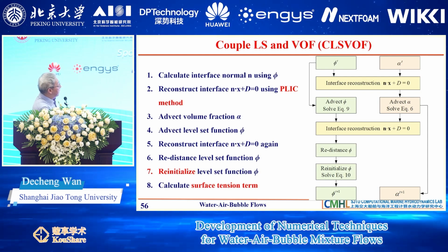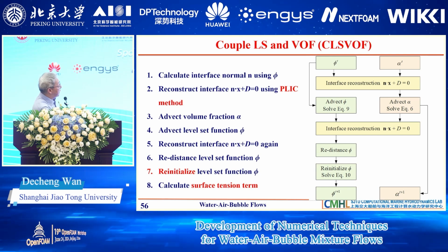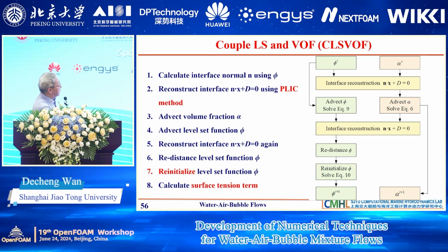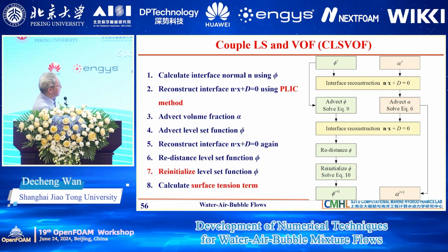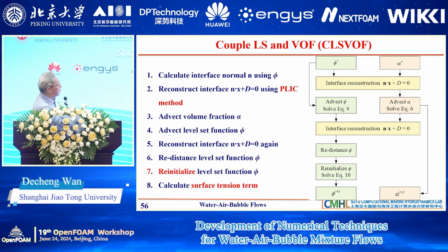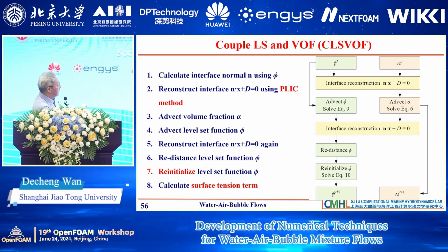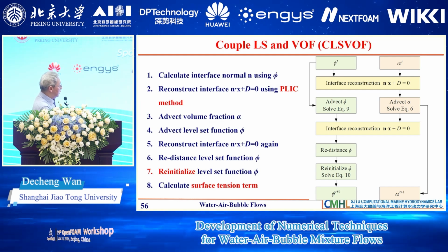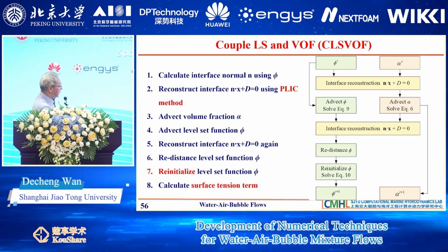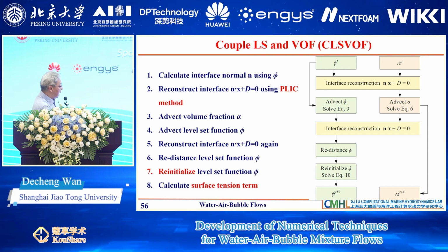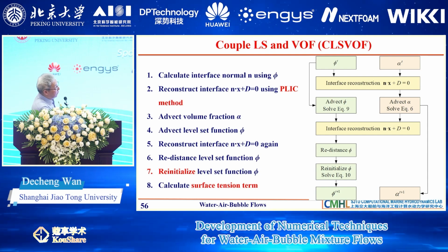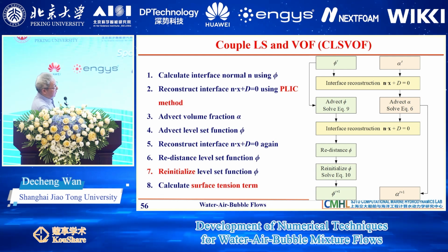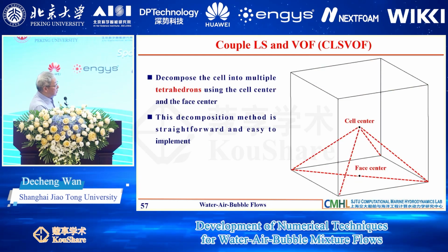We use the interface reconstruction, use this PLIC method to construct this, then update the volume fraction, and then this distance function, the level set phi, so we initialize the phi, so we can couple the VOF and the level set together like this.